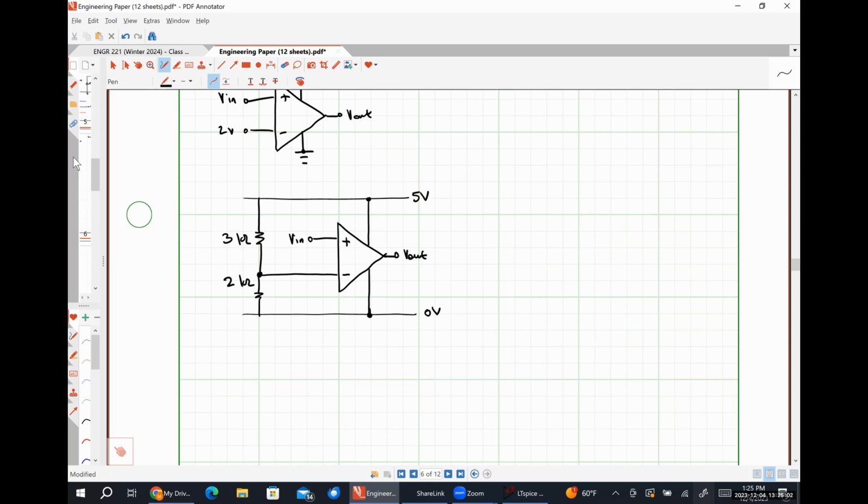So this is going to look like 10 thirds, 10 thirds, 10 thirds. 10 thirds plus 10 is 40 over 3, in parallel with 40 over 3 looks like 20 over 3. 20 over 3 plus 10 over 3 looks like 30 over 3, or 10.